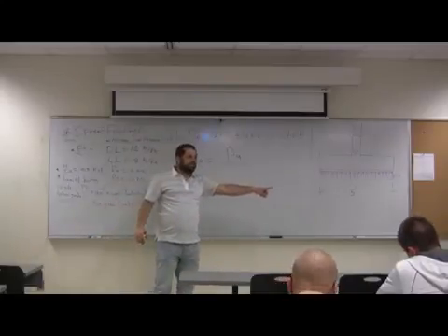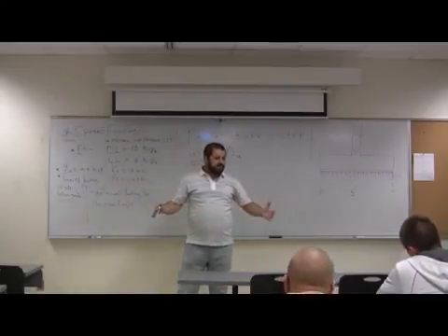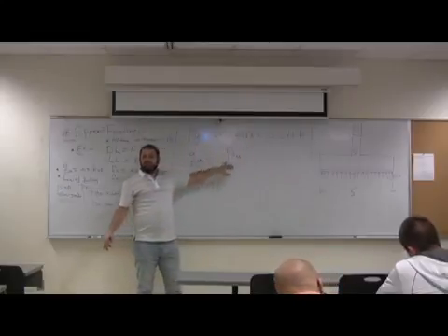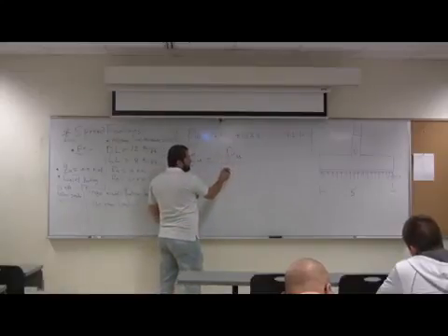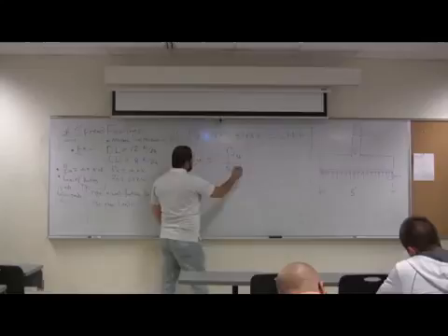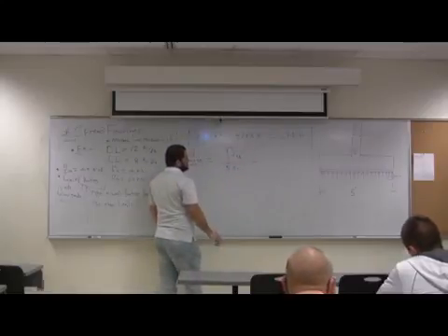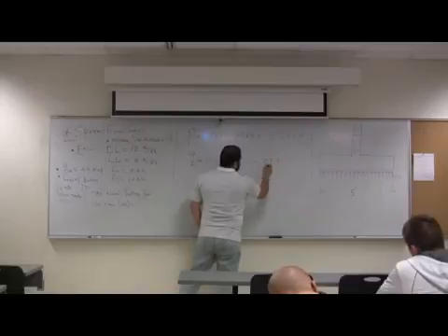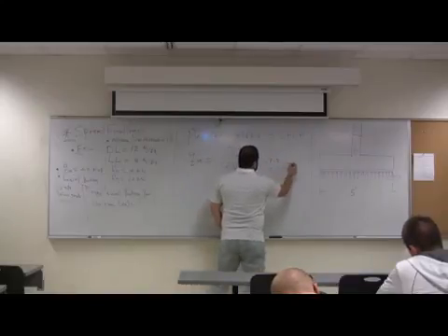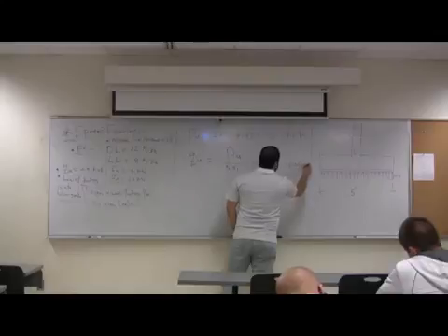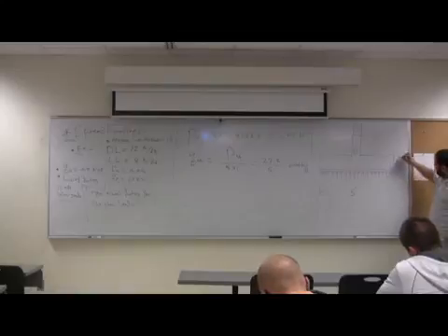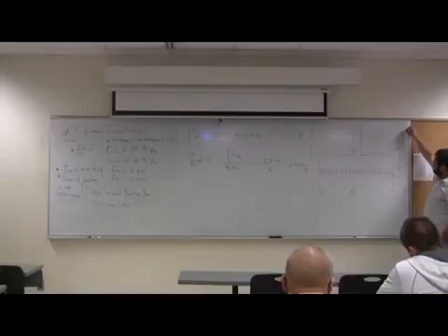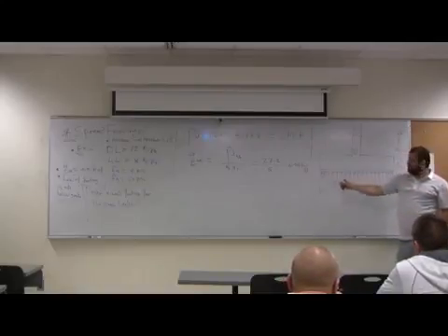Sometimes you need like 4.5 by 4.7, but you picked 5 by 5. So Q ultimate will be P ultimate over the used area of the footing. So this will be divided by 5 times 1, or 5. So Q ultimate will be how much? 27.2 divided by 5 is 5.44 per foot. So that's your Q here. This is Q ultimate equal to 5.44 per foot here.